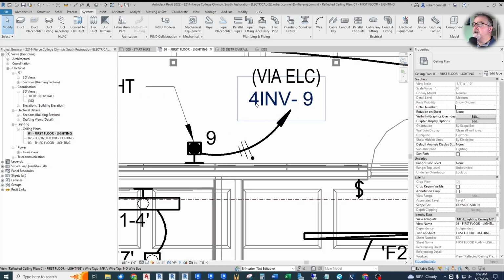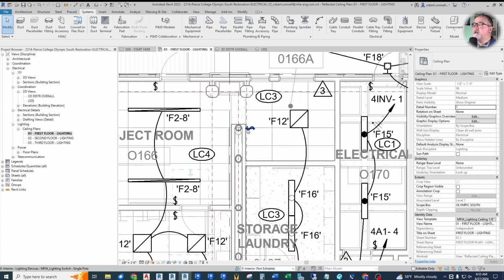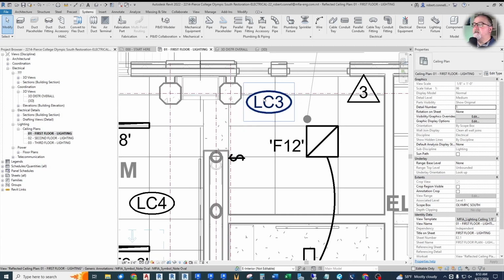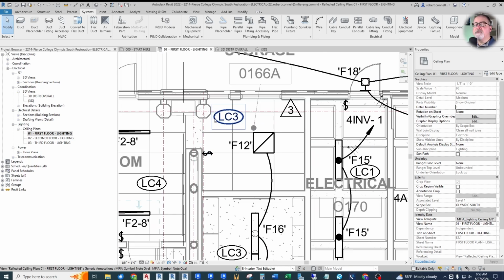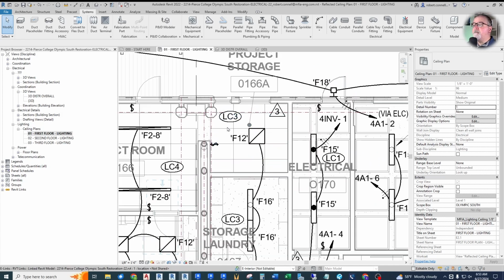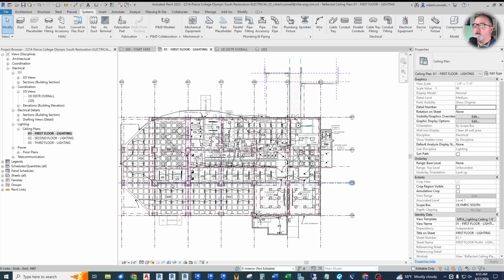We've also created custom tags. As you can see, you can have wiring shown. It automatically will add this wiring and put an arrow on it, and it puts these little tick marks for conductors. We can customize what those look like. We also have little switches shown. Our firm uses a kind of a note to indicate lighting control. So lighting control 3, and then we refer to a legend that explains lighting control 3 may be simply an occupancy sensor type of control. LC4 is something else. So that's how we do it. But you can use whatever scheme you like.